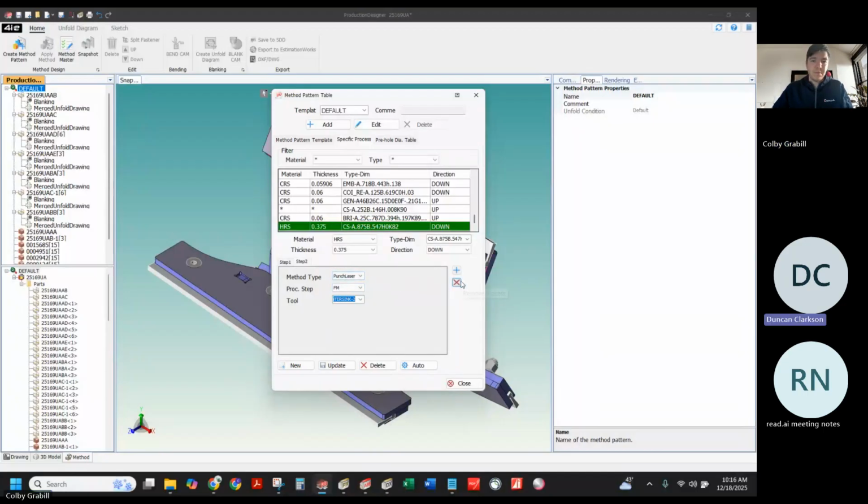Okay. Now, how is it recognizing those features? Is it using the SolidWorks file in its own design tree and looking at the features that were there, or is it just looking at the geometry and taking its best educated guess? It's looking at the geometry and then basically measuring that geometry and the profile of it. So if you have 2 engineers that draw countersinks differently, you would have to set this table up with redundancy: you bring in the first engineer's file, then bring the second engineer's file in, and then you would set both of those geometries up to do the same thing, basically.